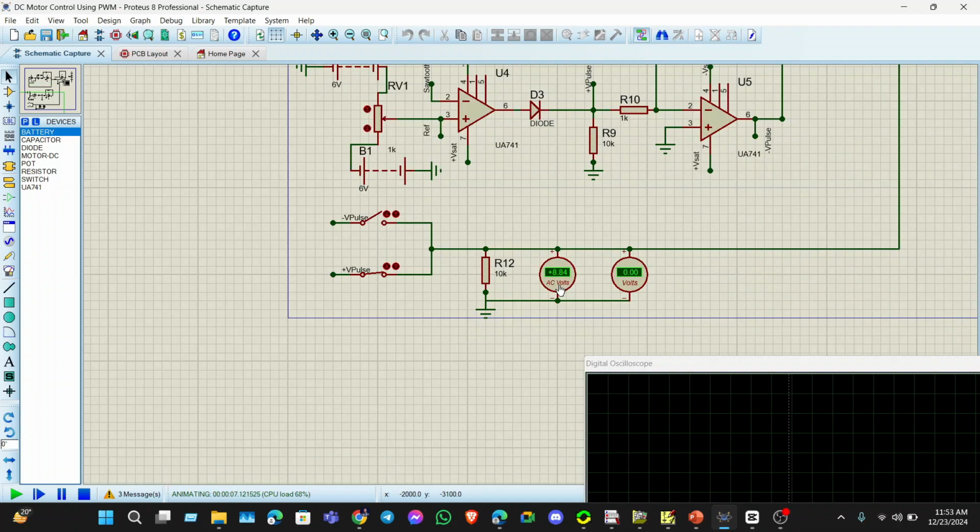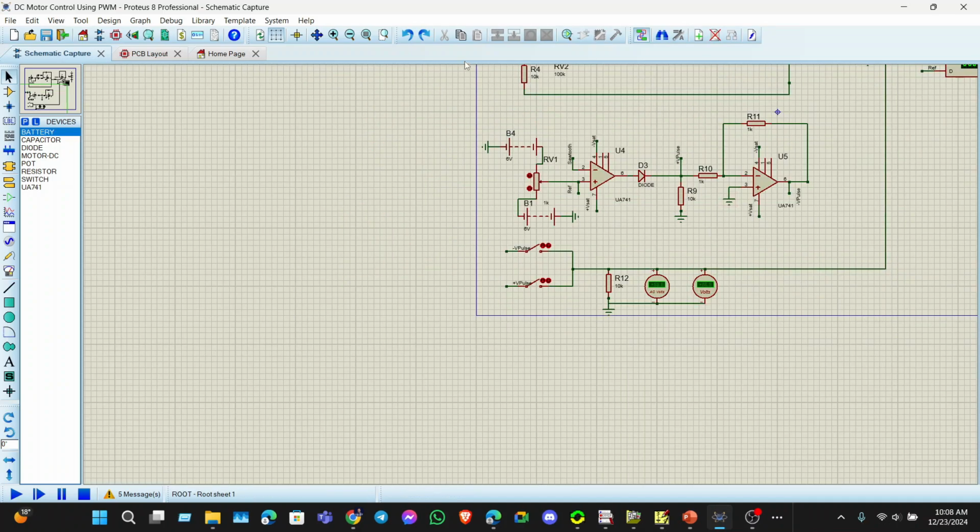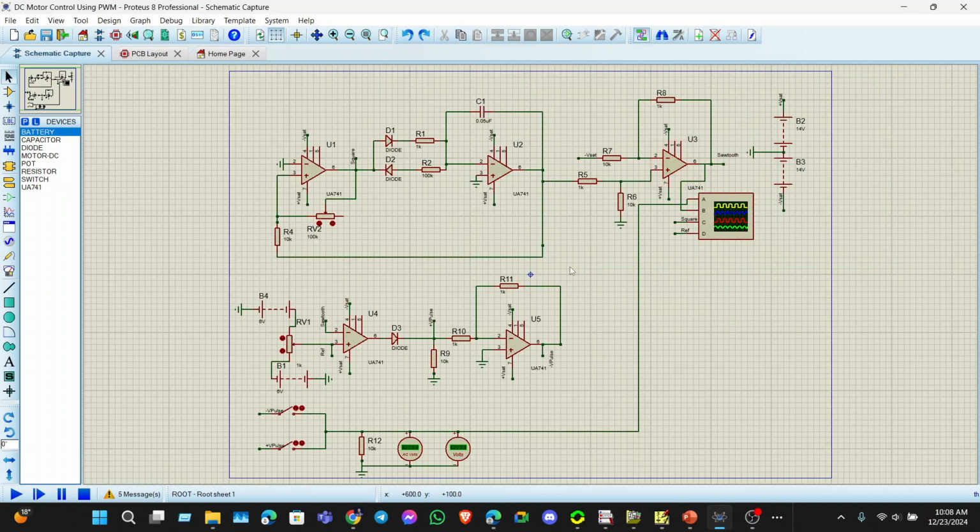As the switches are turning on and off as a square wave, the DC motor will not distinguish between the on and off. The voltage is also lessening. As we increase the reference voltage, the voltage is increasing as the width of the PWM signal is increasing. A DC motor will only count the average voltage. So that is all about our project, and we tried our best to demonstrate it in a very good way.